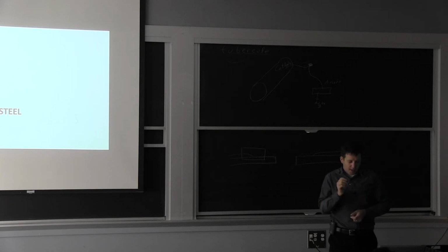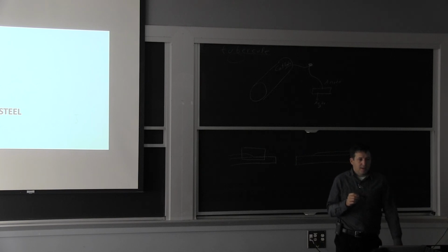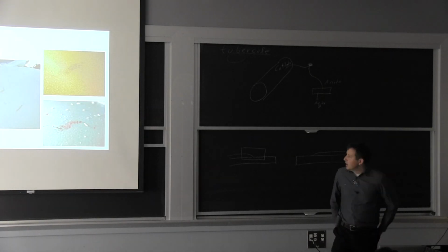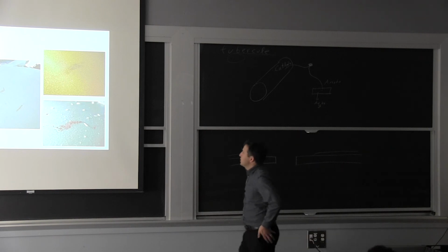But the idea there with the coating is not to protect against just moisture penetration. You just want to prevent the chlorides from getting to the surface. As long as you prevent the chlorides from hitting the surface with the passive layer, you can prevent corrosion.